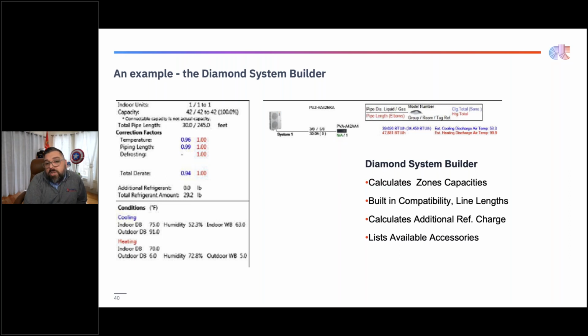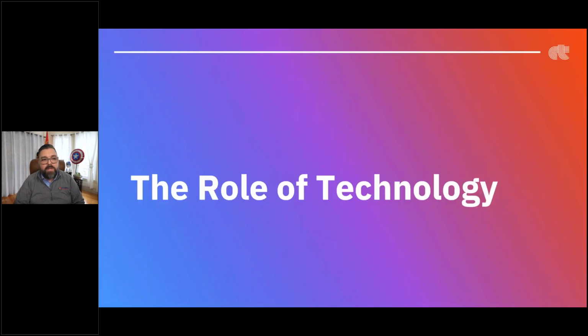So most cold climate heat pumps actually get a better heating performance than what the nominal size cooling is. And we actually select heat pumps based on the cooling size and capacity. So it's not a bad process for cold climate heat pumps. It gets you pretty close. You don't need a lot of supplemental heat if you do this process correctly. And the tighter the home, the closer your heat loss and heat gain tends to be, all right? So we have plenty of time here.